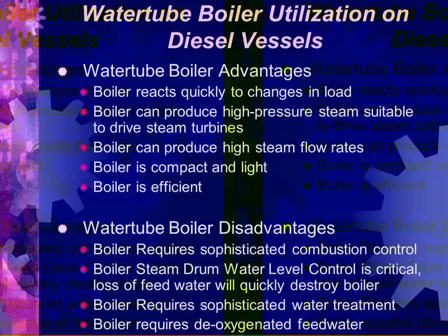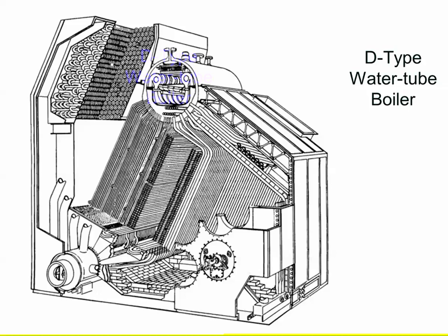The higher the pressure of the boiler, the more it is subject to oxygen corrosion, the more it's subject to scale and other problems and has to have a much better regulated water treatment. So this is a close approximation of what you have in the simulator. Very close to what you have on the steam sim.